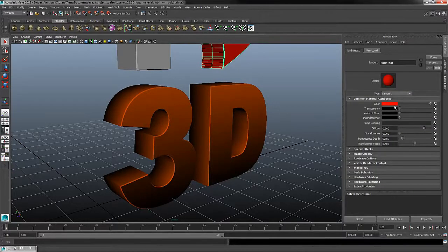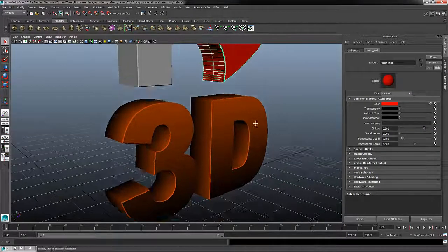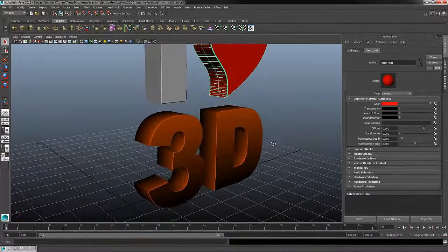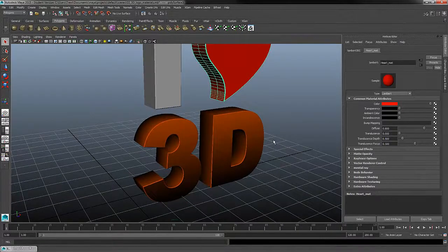Now, by default, we had selected just a color. So in the attribute editor, if I go to my material attributes, we had red paint. We painted our logo red. And if we painted a wall red, it doesn't matter if we paint side to side, up or down, the paint's going to get applied to the wall. And that's fine. Now, if we go to use a wallpaper, all of a sudden, it matters how we put the wallpaper. If we go side to side or up and down, the pattern of our wallpaper may change. So it's important to lay out how we're going to put the wallpaper or our texture on the object so that it lays out properly. That process is referred to as UVs in a 3D environment.